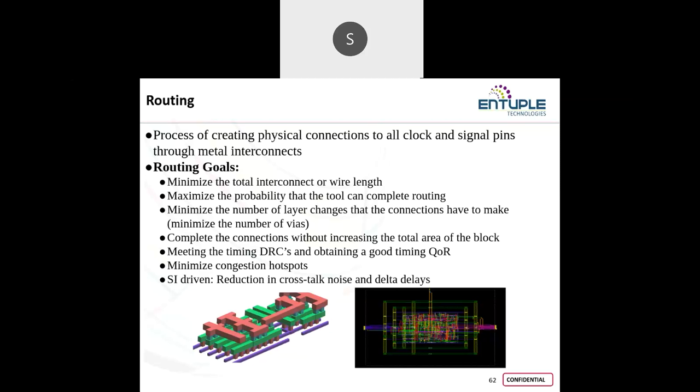And even as I have already told, signal driven is nothing but signal integrity driven. So the crosstalk noise, or even the noisy delay, all those things can be reduced. By reducing or fixing those things, the quality of my routing results will be a better one.